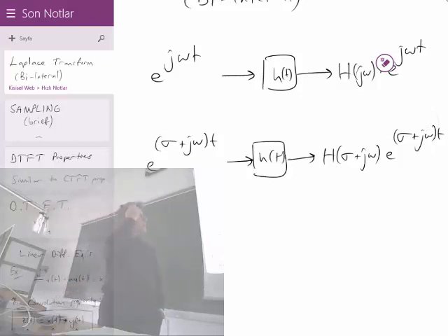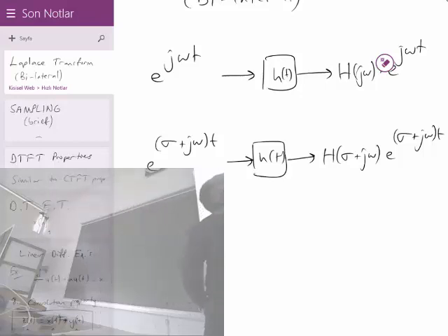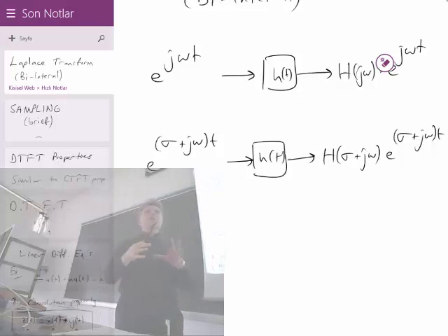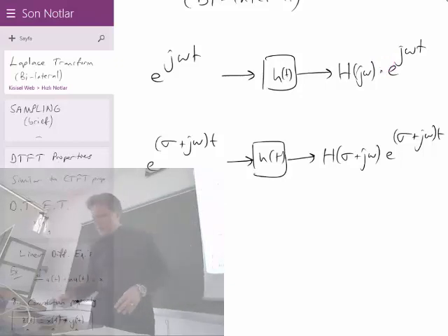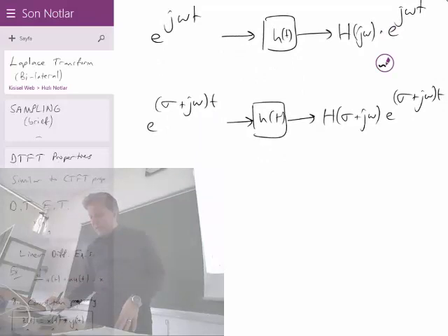This is a more generalized way of imagining or considering the input-output relation. Do you remember what I call such signals for LTI systems? These are LTI systems because they have impulse responses. They were called the eigensignals, I said, because they look like the eigenvalue, eigenvector situation. It's like the eigenvector. This one in geometry is like an eigenvector of a matrix. What was the property of an eigenvector for a matrix? Let's say that the matrix is A and the eigenvector is V.